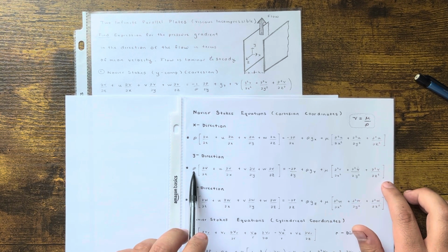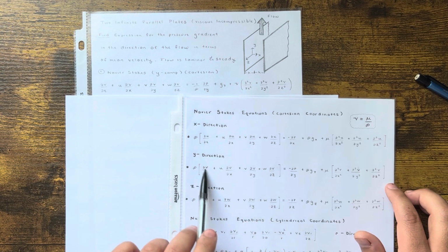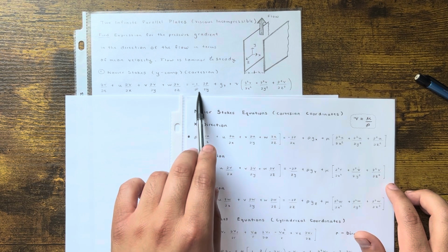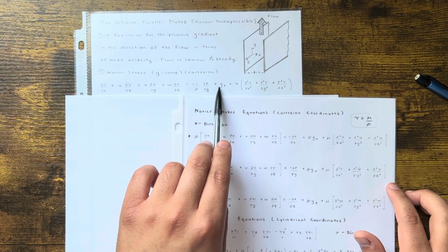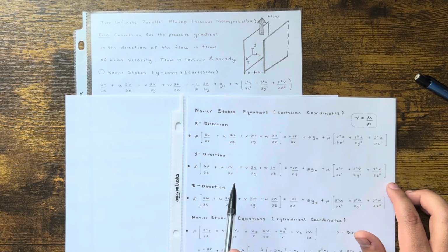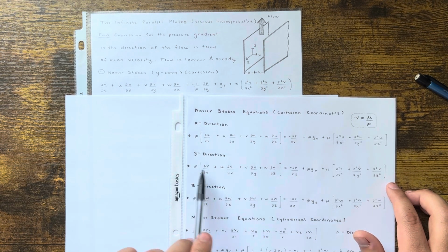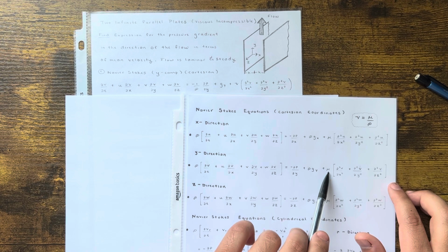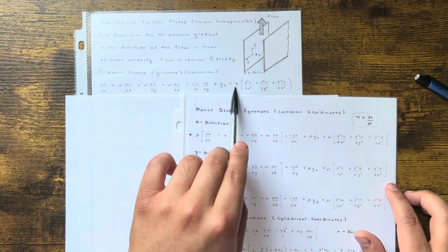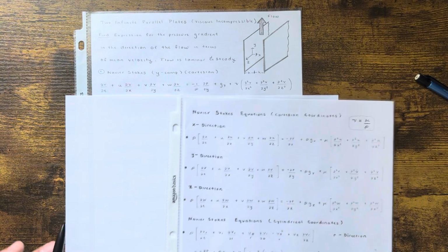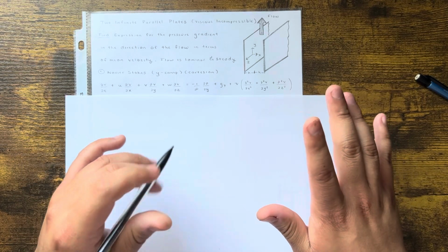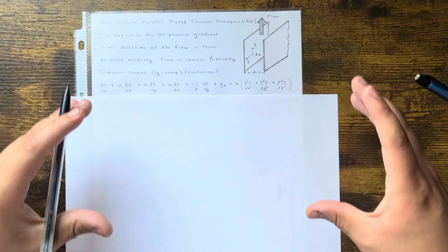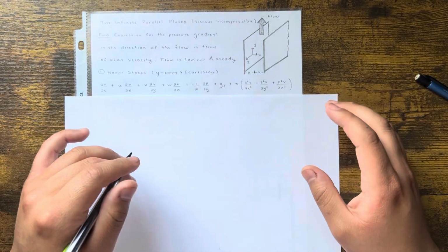But what I like to do is I just like to divide by density to everything. So all this stays how it is, right? Up to here. You have a -1 over density, right? Because this is negative as it is. You have just gy, right? Because that density went away. You divide it by density both sides. And then mu over density, that's just nu, okay? So I just replace it there, and then that's it, okay? No big deal. So we start off with the equation, and it looks scary, but you just start simplifying from here. It's pretty straightforward. You'll see that this crazy equation kind of just reduces to very workable terms.